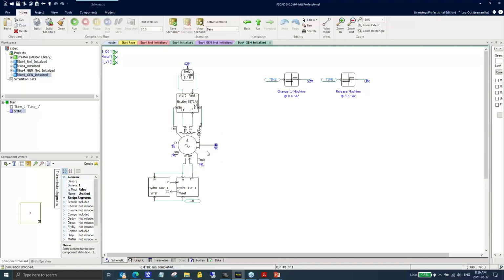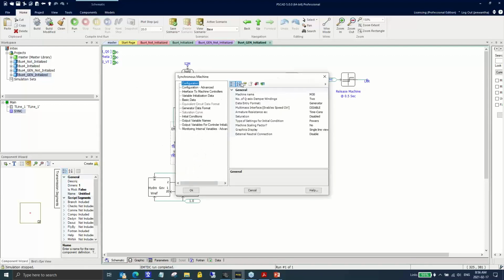Once you provide the initial load flow conditions, the PSCAD blocks, exciters, and governors are already pre-programmed to perform a back initialization. So that's not a part of the load flow initializer. The load flow initializer just gives you these initial conditions: terminal voltage, expected power, expected reactive power, and the bus angle. You can see that these are variables. They are updated through our initializer.